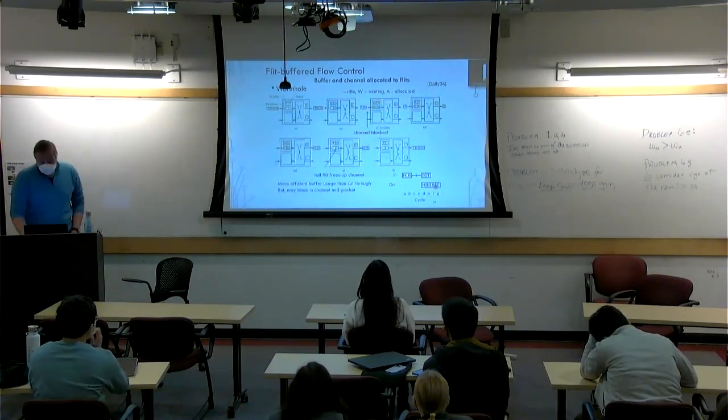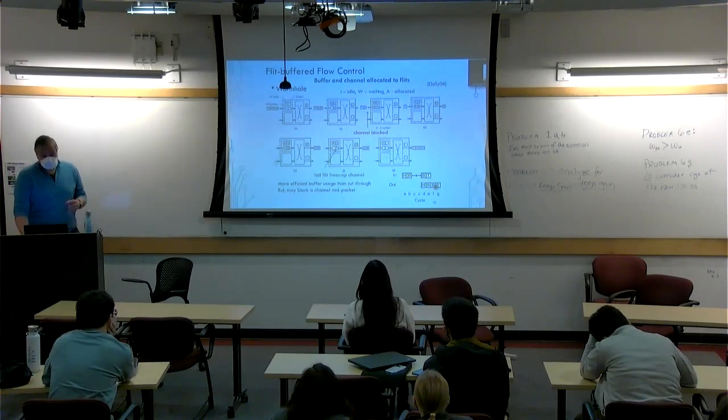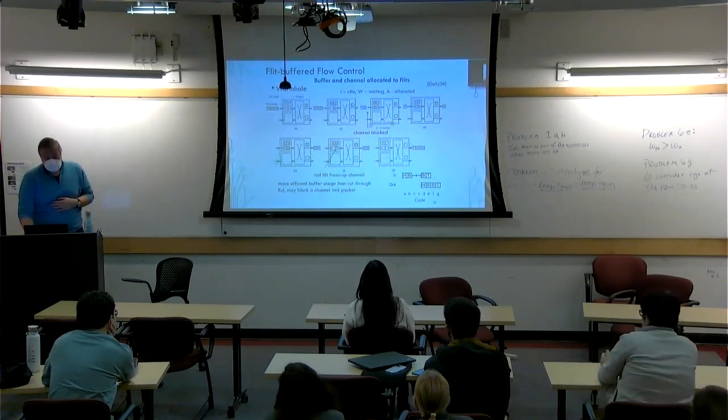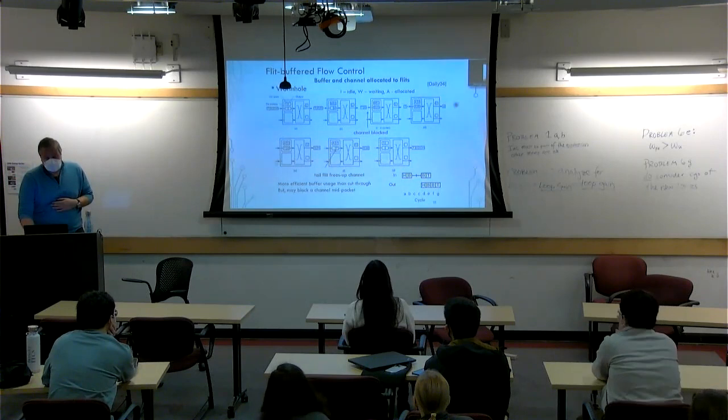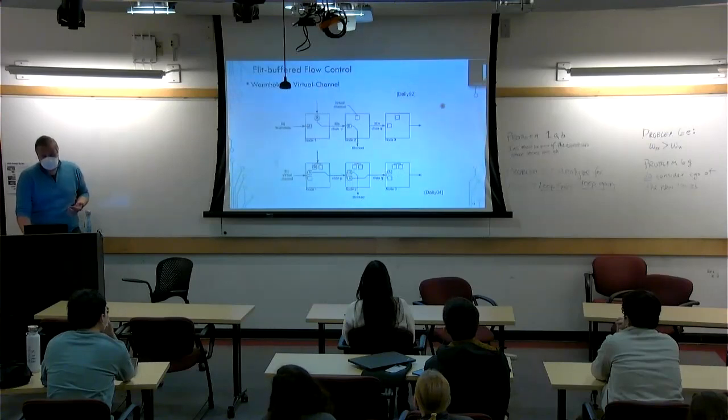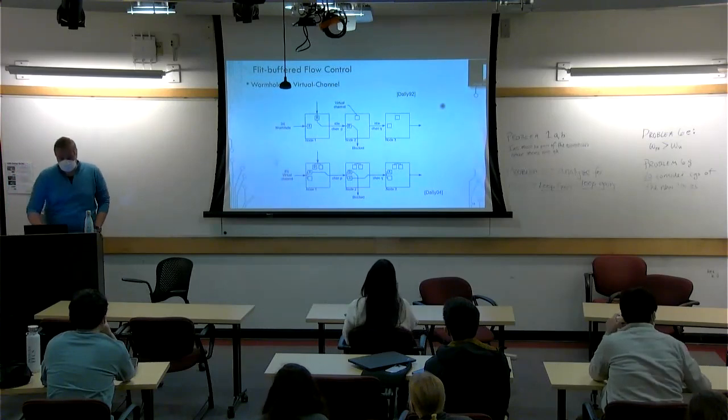Okay. Now, this is effective because I'm dealing with flits and I'm reserving the buffer. I'm able to make headway just based on what downstream stuff is available for a single flit, not for the whole packet. But I can still get, let's call it, a head of the line blocking type of thing.